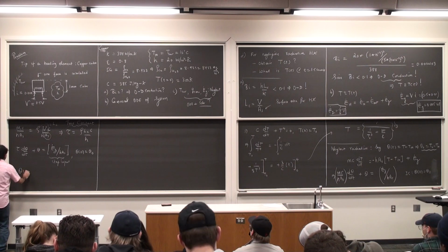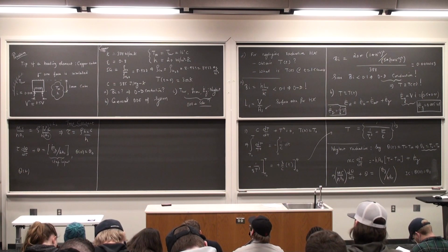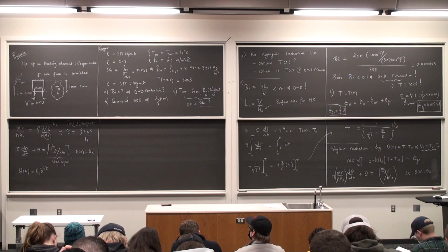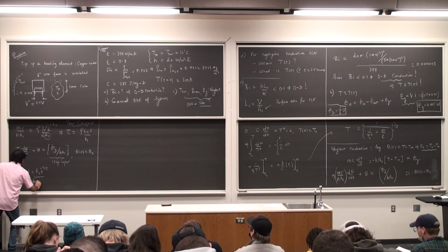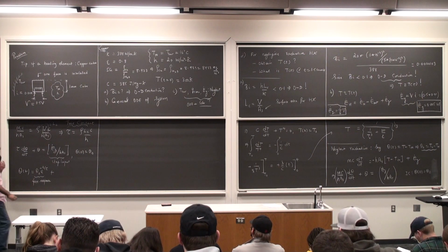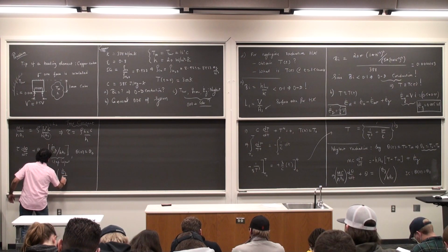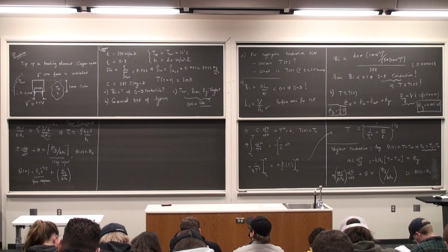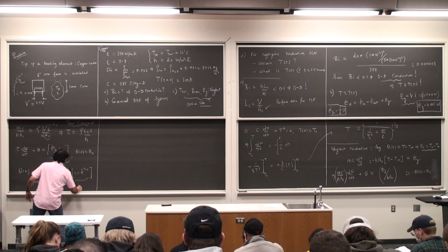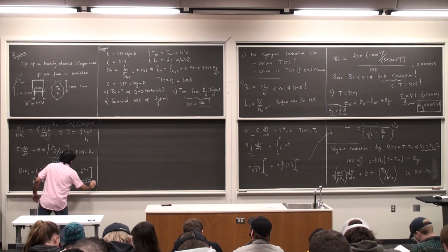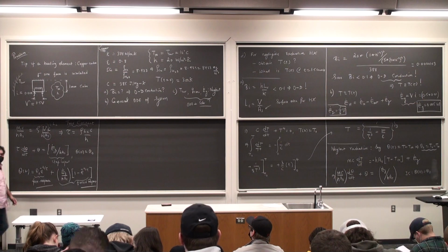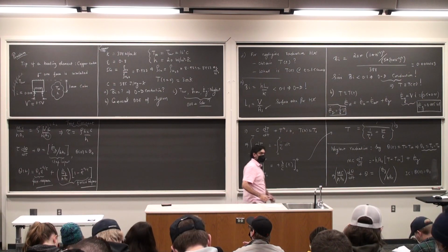So theta of t, after solving, is going to have two pieces. The free response, which is theta naught e to the power minus t by tau. This is the response to the initial conditions. And then the response to the step input can be written in the following manner. This is the magnitude of this step input times 1 minus e to the power minus t by tau. This is the forced response. Does this make sense to everybody? You remember these things from system dynamics vaguely? Okay.